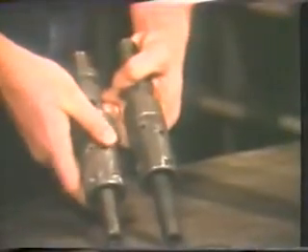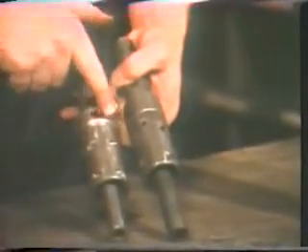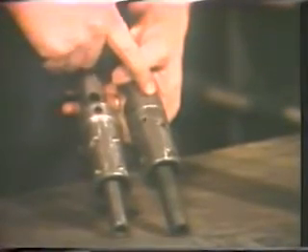The C1 running tool may also be used to set the lock in other F nipples, besides the top one of its size, by replacing the locator ring with a thread protector.